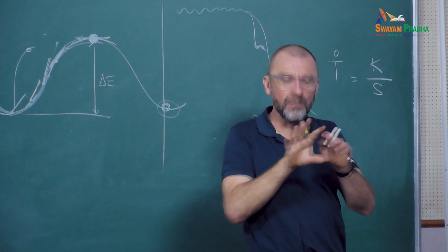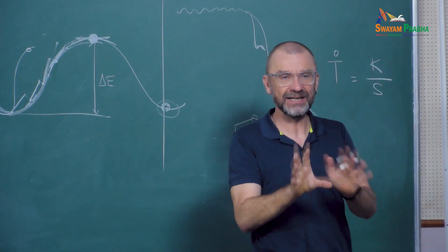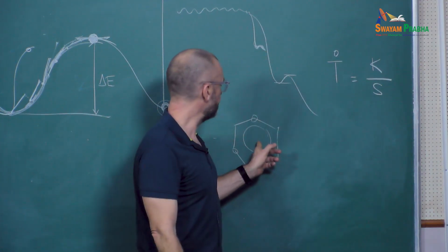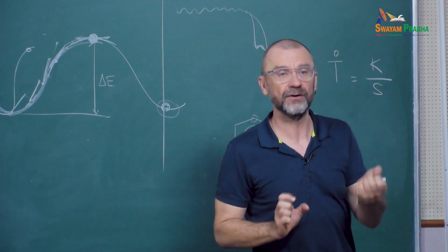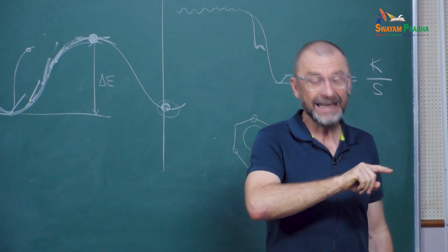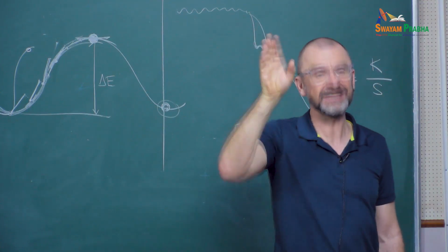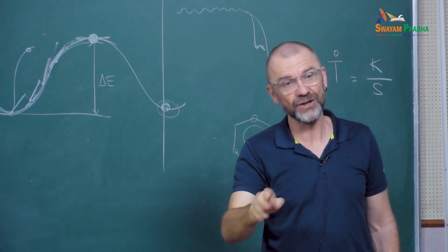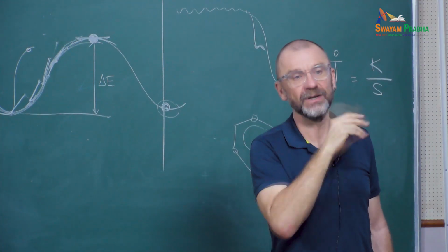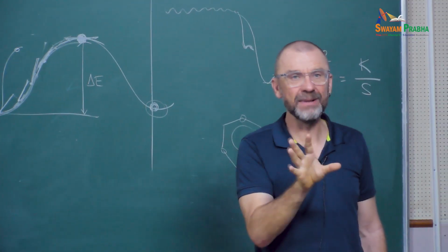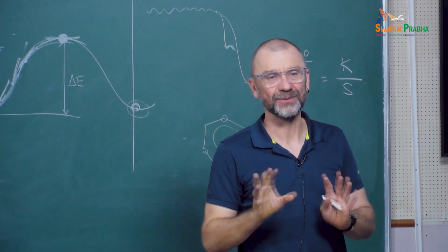One way to measure in the structure what is the level of relaxation is to count the number of big atoms surrounded by an icosahedra of first neighbors. That number increases with the relaxation of the glass. So the lower the quench rate, the higher the number of icosahedra, for example. But it remains an approximate measure of the structure, but it works quite well.